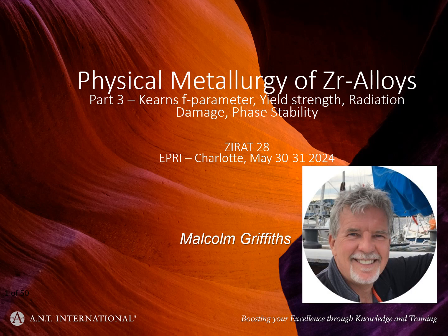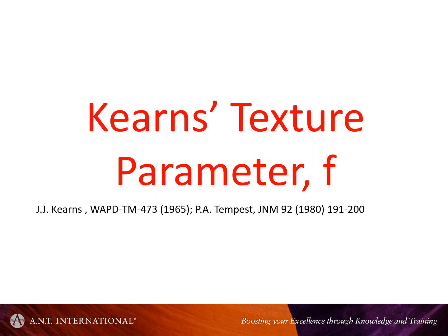Okay, welcome to part 3 of these lectures on physical metallurgy of zirconium alloys. In this lecture, I'll be talking about Kearns F parameters, yield strength, radiation damage, and phase stability. We'll start with Kearns texture parameters, named after J.J. Kearns, who worked at the Bettis lab back in the 60s.